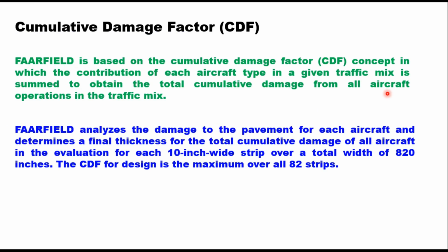FAARFIELD analyzes the damage to the pavement for each aircraft and determines a final thickness for the total cumulative damage of all aircraft in the evaluation for each 10-inch wide strip over a total width of 820 inches. So the total pavement width is divided into 82 strips of 10-inch wide, and damage is calculated in each strip, and the CDF for the design is the maximum over all 82 strips.